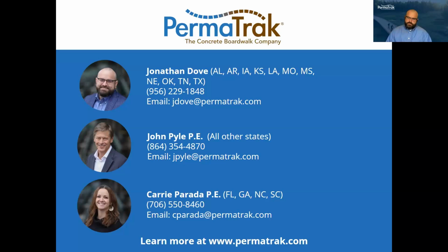Yeah, John, I'll start with that, and John Pyle has a lot of experience with it. He might want to answer it also. Let's consider a very typical average size boardwalk. 100 to 200 feet long is very common. And when you approach the geotechnical engineer, I would highly recommend that first you understand what the loading is that you're trying to design for. Look at a range of how big your spans can be. Are they 10 to 20 feet, 30 feet? Determine what that range of loading is.